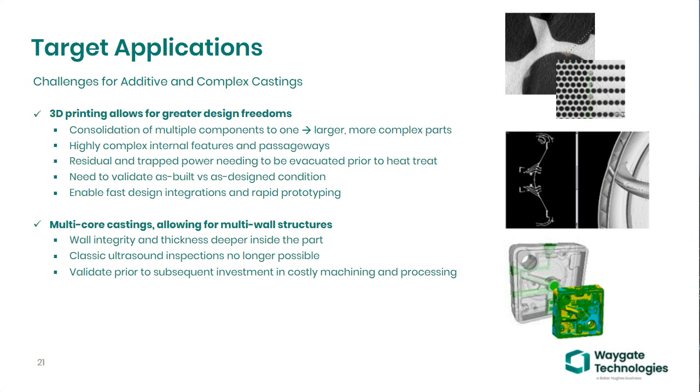And then the multi-core castings, I know some of you are pretty familiar with those, but looking at stuff that was previously done with wall thickness measurements by ultrasound, and doing them now with CT, you can get through those multiple walls and look at the wall integrity, the wall thickness, et cetera.